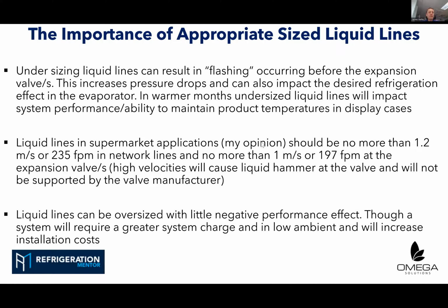Where I kind of laugh about it, it's everything's 3/8, 1/2 inch, and there's not much in the way of sophisticated design that goes into them. Yeah, because another thing that came up was that in some situations there are liquid line pumps, because if you've got a 400-foot run, the velocity gets so low that you have to put a liquid line pump in there.